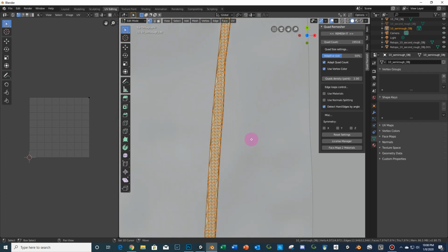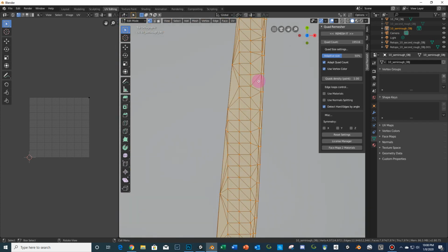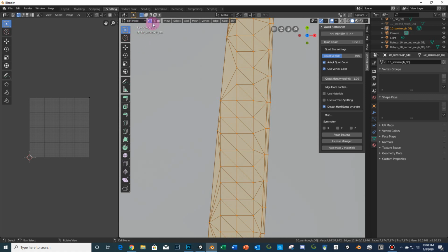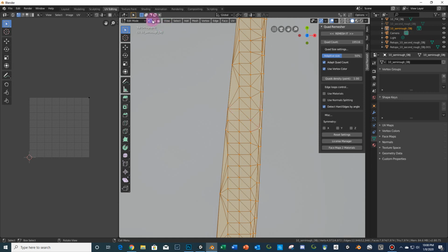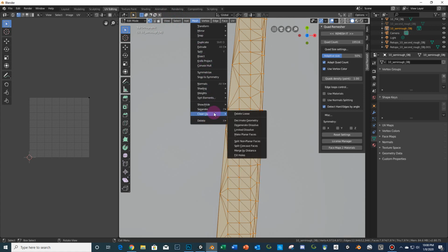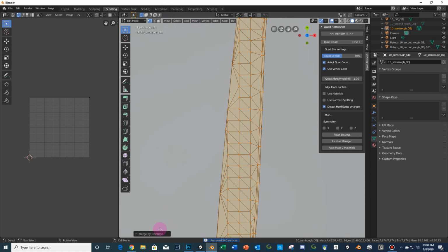And the way the semi-rough is done is you first have to clean up the mesh because the points here are not joined. So if you go to vertex select and I move this because of the blend, you see the points aren't joined here. So we have to join our points, which is just basically removing our doubles. And so in the new way to do this, you go mesh, clean up, merge by distance. I change my merge by distance to 0.001, hit enter. So you see here removed 540 vertices.